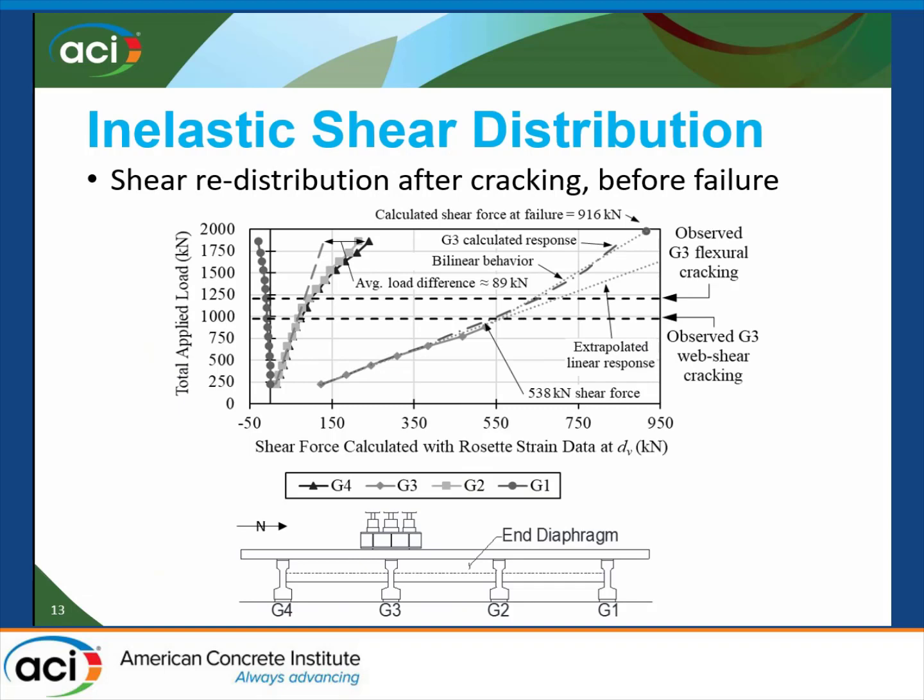So here's a big picture that I'm going to take some time to explain, and there's a follow-up one, which is looking a little bit at how the shear redistributed after cracking and just prior to failure. So on the x-axis, I've got the shear force in each beam that was calculated with the instrumentation. So if we're looking at the one I loaded, what's the amount of shear based on shear strain, converting that to a force.